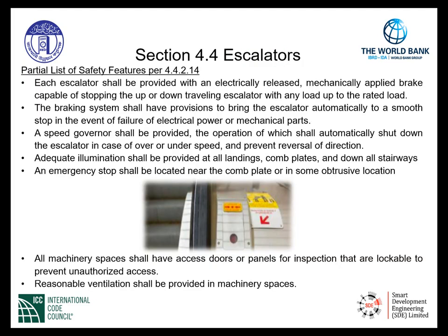A partial list of safety features according to section 4.4.2.14 is given here. The first item in this partial list is that each escalator shall be provided with an electrically released, mechanically applied brake capable of stopping the up or down traveling escalator with any load up to the rated load. The braking system shall have provisions to bring the escalator automatically to a smooth stop in the event of failure of electric power or mechanical parts.